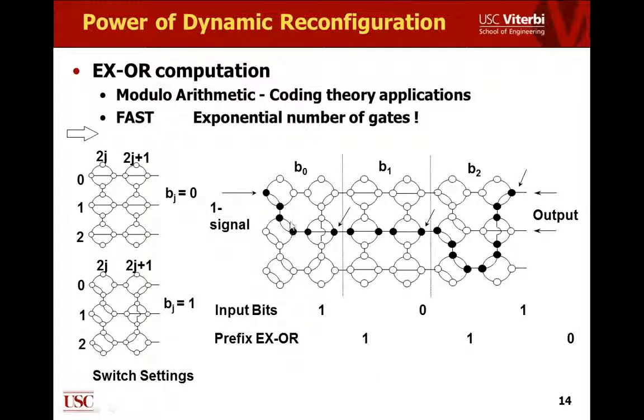That means that if I have these connections here, I cannot have this processing element as well as this processing element trying to send some signal on this. There will be conflicts on this bus. The other rules include, to address the concern about what happens if there are loops, that we will ensure that there are no loops in this connection. If there are loops here, signal will propagate through all of them. If we do have the loops, we can also make sure the loops are okay by ensuring that exactly one particular signal will be put on this bus. So I think the short answer to the question is that we have to design the algorithm so that the physical properties of the device on which it is going to be implemented are satisfied. We cannot have multiple processing elements talking at the same time on the bus.